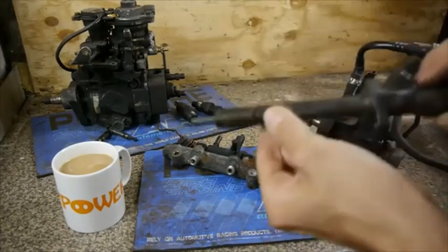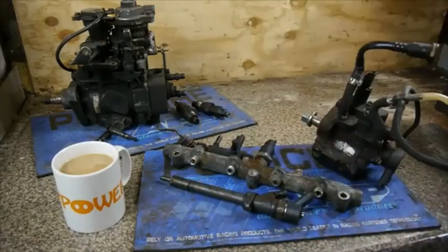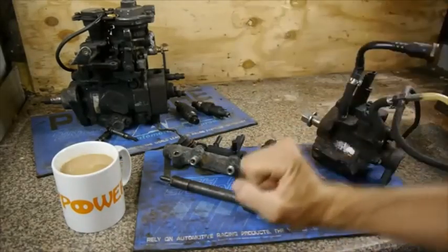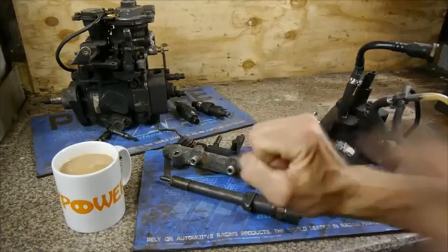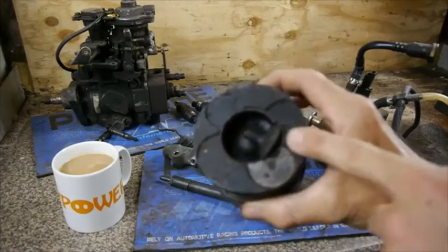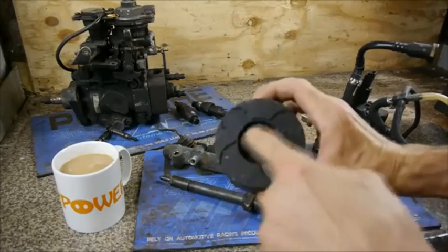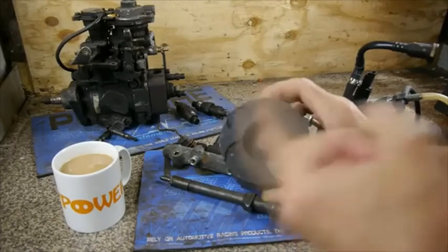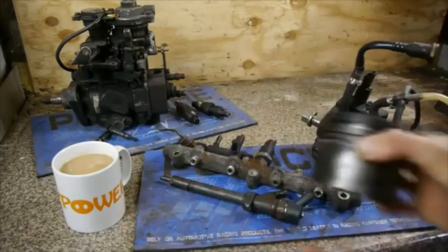Hence the pistons are often different on the direct injection as the indirect injection. Indirect injection, the piston comes up and it's got a flat head to it. And a direct injection system, well, that's a little bit different. Let me show you what happens when it goes wrong. So we have a valve in the middle of ours, that's from the lemon, but you can see there's a bowl in the middle which helps create a swirl effect to help the fuel and the air mix.